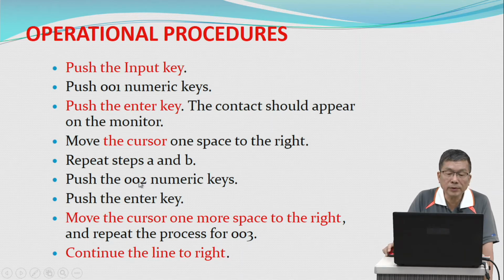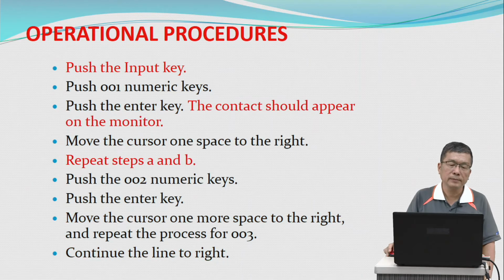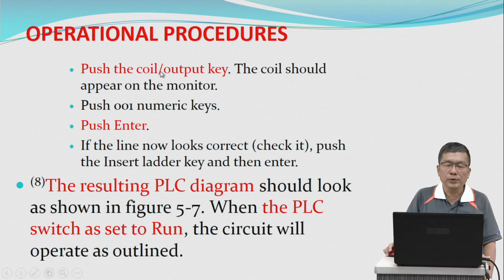Push the 002 numerical key. Push the enter key. Move the cursor one more space to the right. And then repeat the process for 003. Continue the line to the right. Push the coil output key. The coil should appear on the monitor.